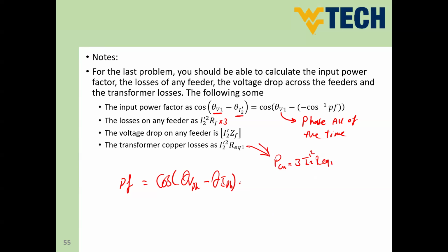Okay, nice. Here, guys, if you remember that we have core losses, and we use this term in the open circuit and short circuit test and parameter identification, so we can get the core loss from the open circuit test. If you can see here in this question, we don't have this core loss. It's not mentioned, which means it's neglected here in this example.